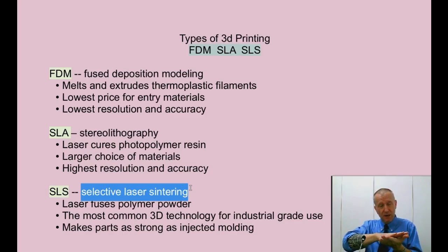We can put a little on the shape and compress it until, at the molecular level, it will bond and join together. Or we can use what's probably the best way, I think, fusing with lasers or heat, in which you put one layer down and then another layer of powder will fuse with the bottom layer by heat or lasers.